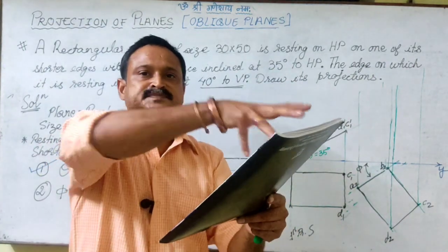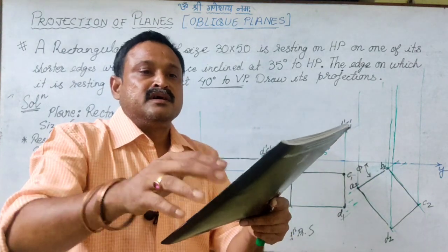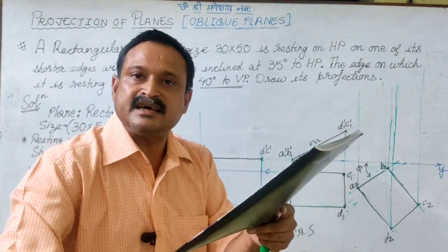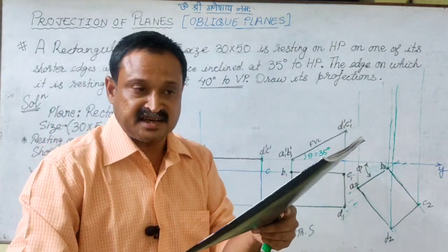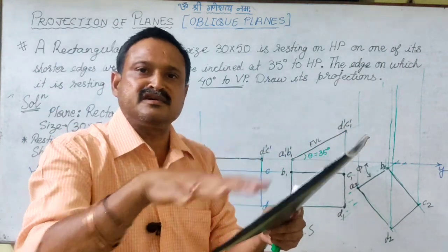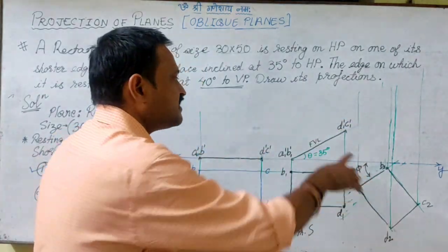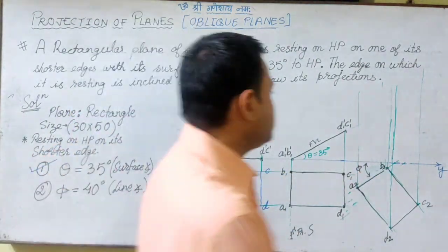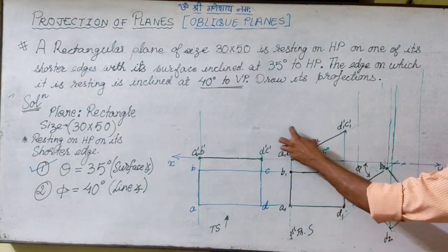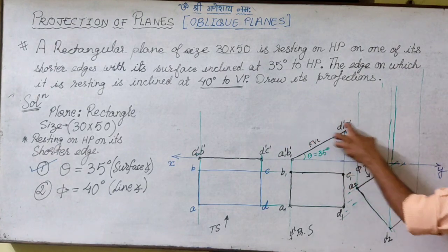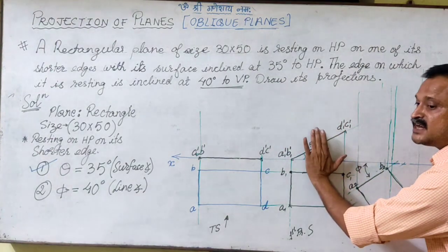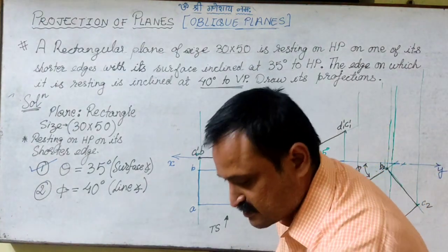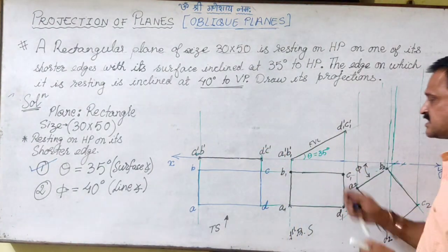We have drawn the projectors, right? Now, we have not changed theta. So if theta is not changed, that means the heights of all the corners remain the same, which is available in the latest front view, right? So that means I can simply drag the heights of all these corners from the latest front view condition of the first condition.